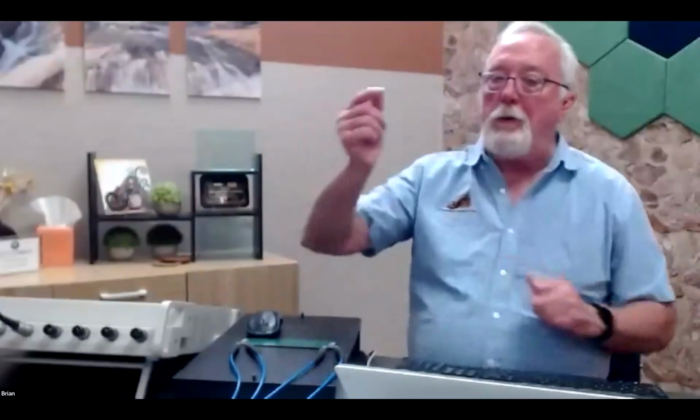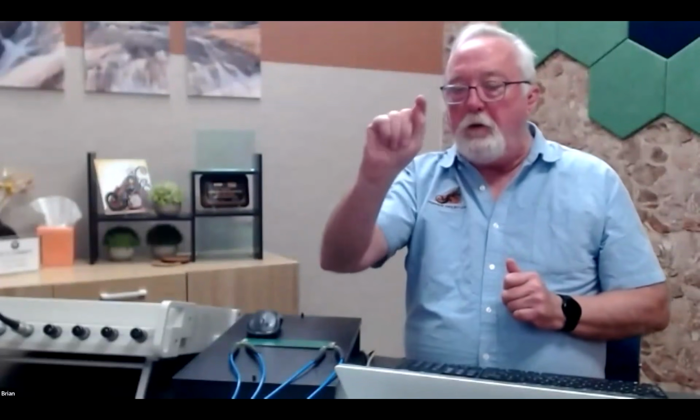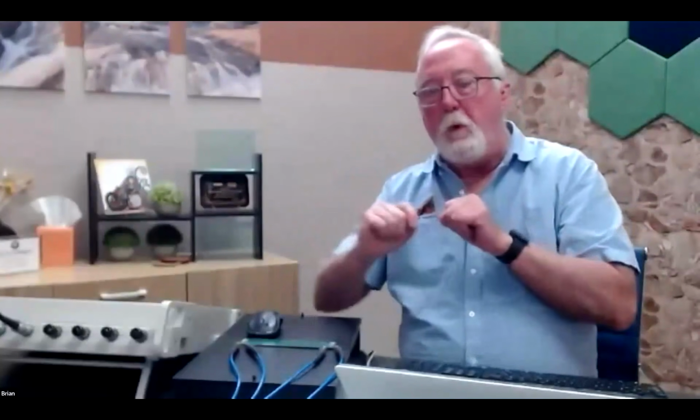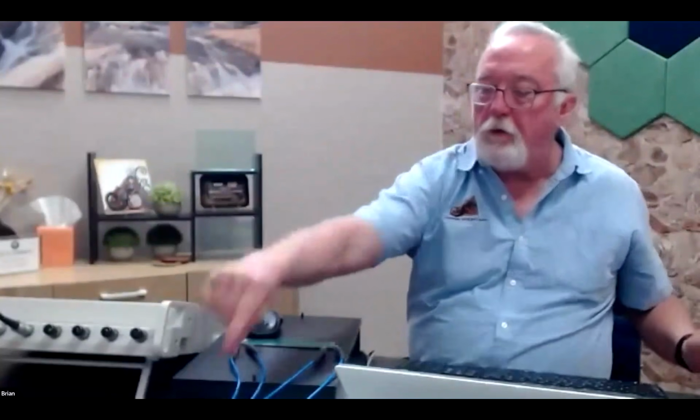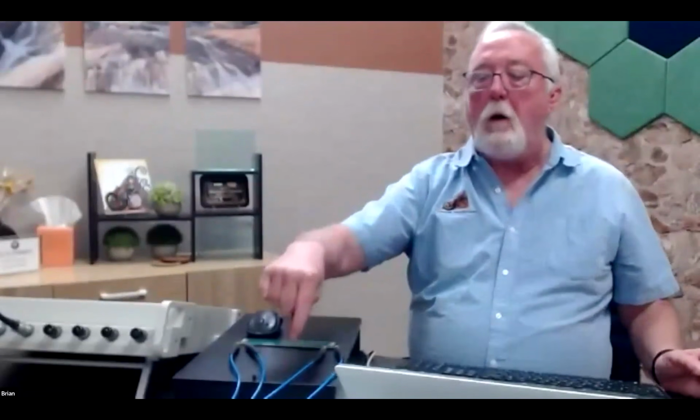Now, again, Picotest has little probes that you can just hook the cables to, ports 1 and 2. It has a single probe which is connected to both ports and a ground, and you would just touch it to your PDN, to your power and ground, and you make your measurement with that. So you might have a look at that. I'm not sure which ones; go to their website. They have a number of them. Your choices are going to be the pitch between the hot part and the ground. They're all pretty much made the same way, though.